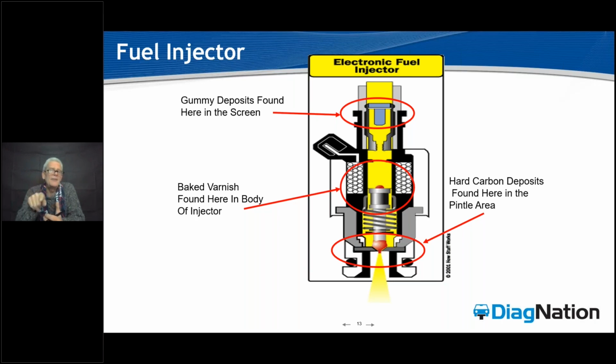And when we have these ghost lean codes that we're seeing, where you're smoking the engine and all kinds of crazy stuff, your fuel pressures are good, you're scratching your head, you're like, what the heck is going on with this car? I've caught many of them in the last couple of years where you pull that rail out and flip those injectors over and tap them and clean them, put them back in and run a rail service on it, car straightens right out.